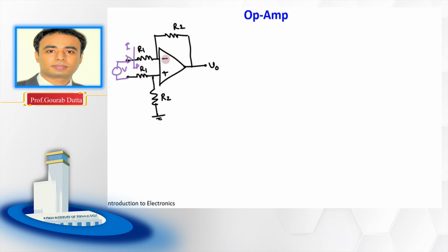Okay, but before we proceed, one thing we should notice here is that this op amp is an ideal op amp, right? So if this is an ideal op amp, then the virtual short concept applies, and due to the virtual short, this potential and this potential will be the same. So we can consider that these two potentials are actually shorted, even though it is a virtual short, right? In that case, if you want to quickly estimate the current, then in this circuit, you can see it here.